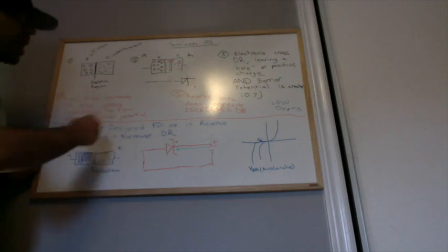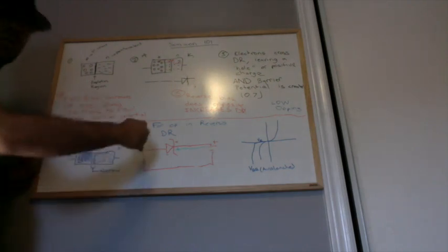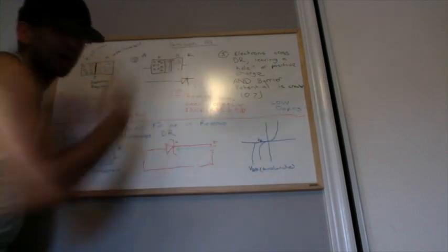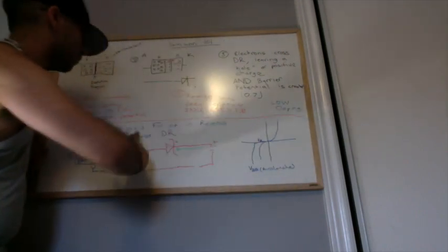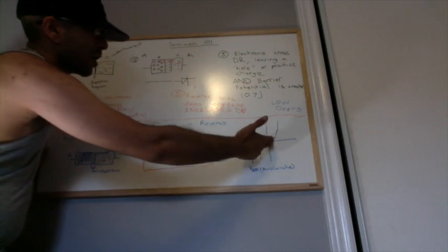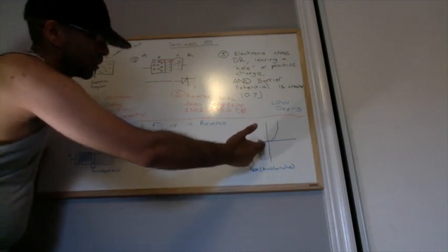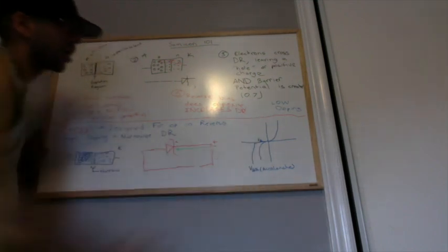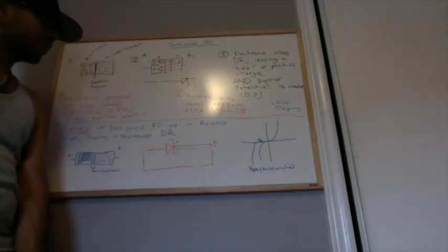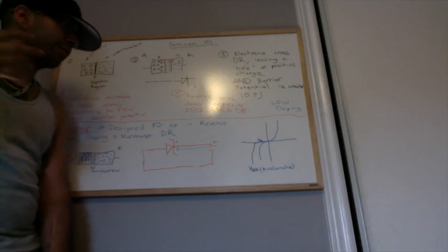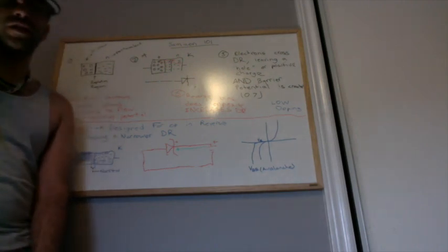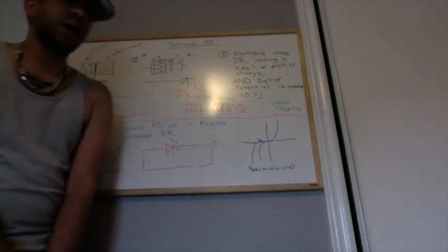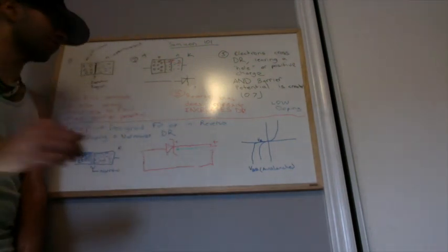And of course I am talking about Zener diodes operating in reverse. In forward bias they operate just like a regular diode. So when we apply voltage to a Zener and we reach a Zener effect voltage, one of our professors has always referred to it as breakdown voltage. That's a little bit wrong, because the breakdown of a Zener diode is very different from the Zener effect.